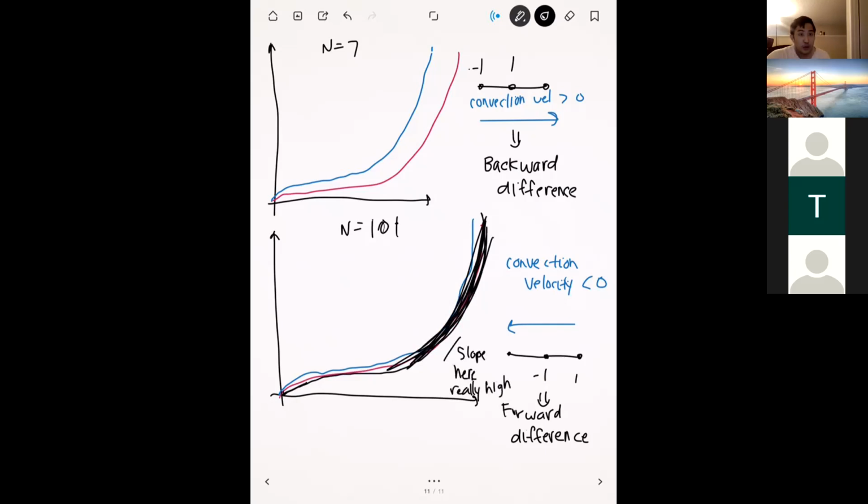you can selectively refine your grid only in those areas. Because like we talked about before, when you refine your grid, you usually increase your cost by a lot. But usually there's only one specific region in your simulation which is causing the issues. And so if you know what that area is, either based on some data or based on your knowledge of the exact solution, you can selectively just refine the grid in that area. You get an accurate solution there, but you don't kill yourself with the cost. That's one way that you can use knowledge of the exact solution or data in order to better inform how you simulate it.